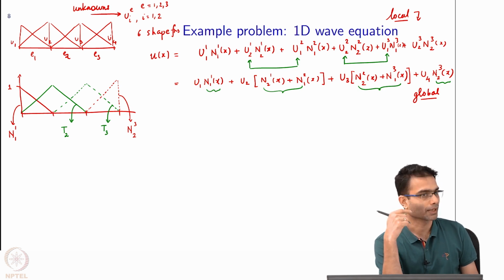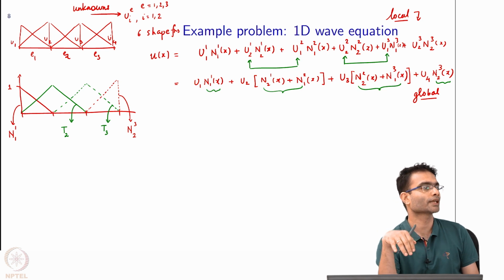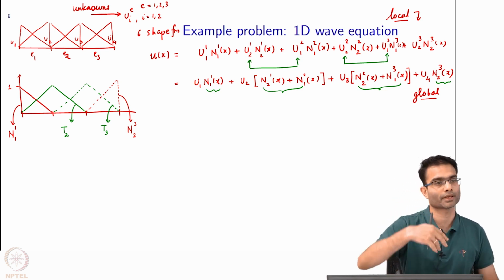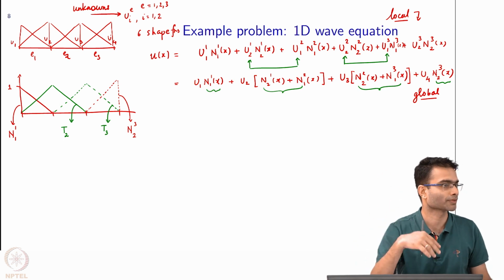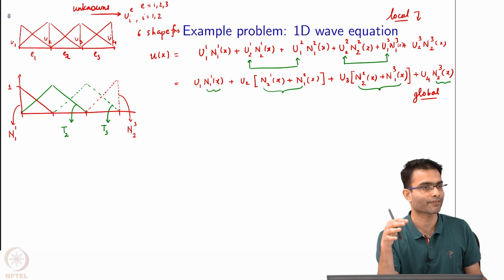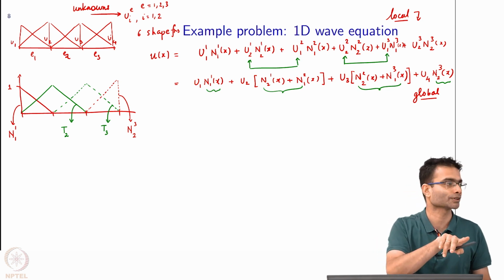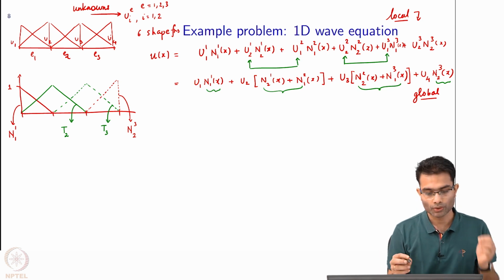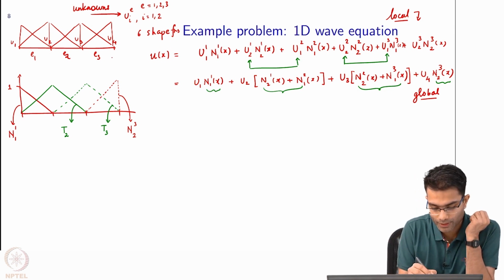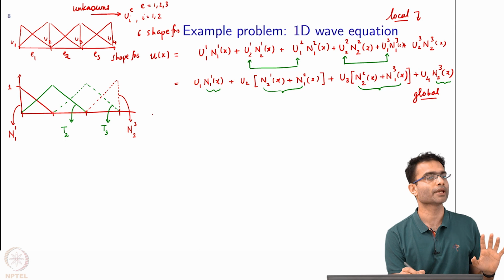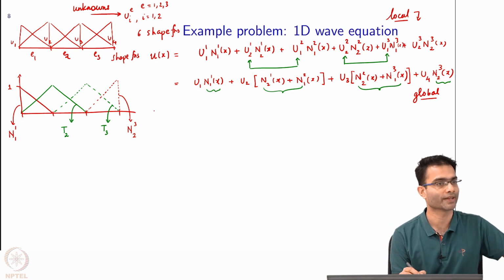It will turn out, and you can work this out, that 2 of those equations are redundant, as they are linear combinations of the other equations. To avoid that, I have combined adjacent shape functions, for example T2 and T3. The ones above are my shape functions, and these that I have drawn are what I will make into my testing functions or weight functions.